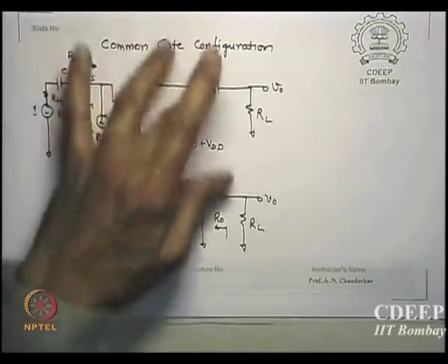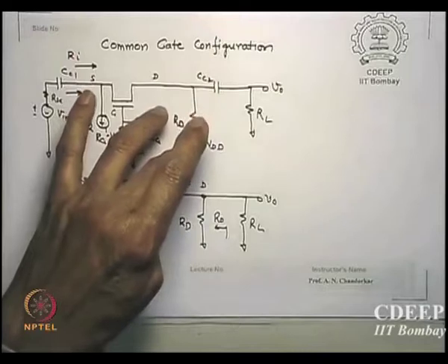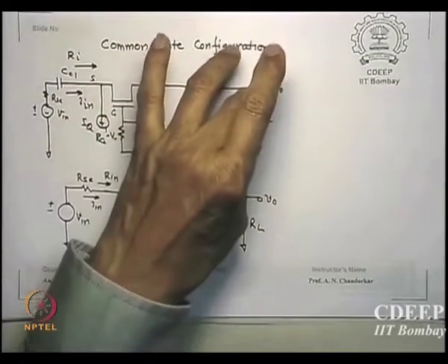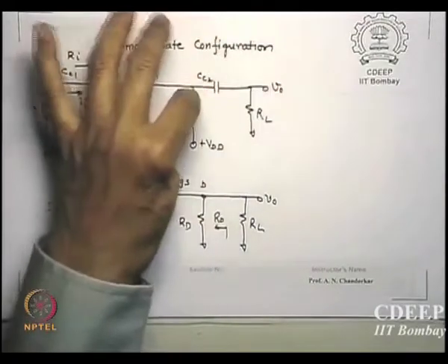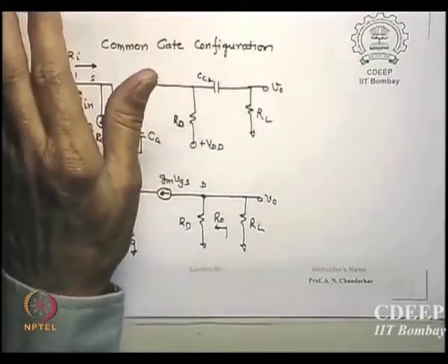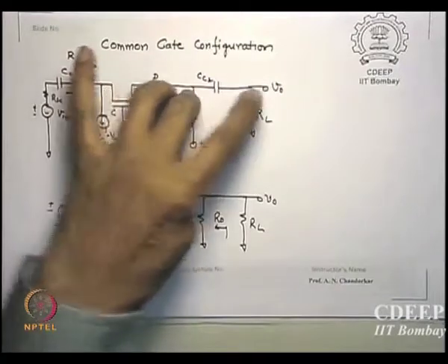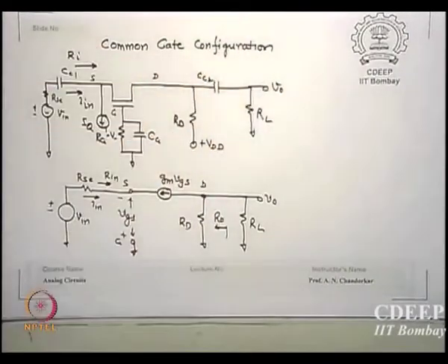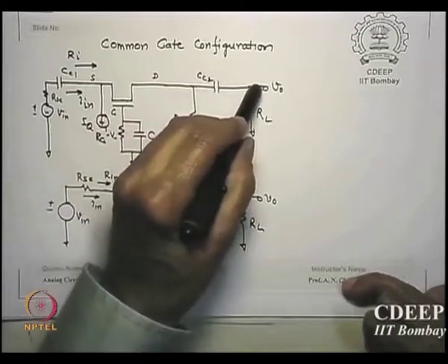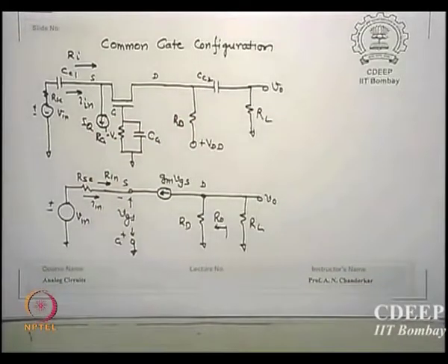No. This is my device. This is the actual load of the transistor. This is the external load. So before I get the external load here, I want it decoupled. This VDD should not go to the output. So I just decoupled it. Is that okay? This VDD should not go to V0, so I have stopped it.